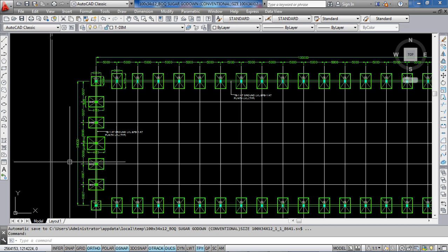In most of the cases, we use 10 feet length sheet, and when we place the sheet over the purlin at the end, a minimum overlap between the two sheets should be 150 mm to avoid leakage. It is the minimum 150 mm. So depending upon the length of the sheets and minimum overlap, we decide the spacing of the purlin.